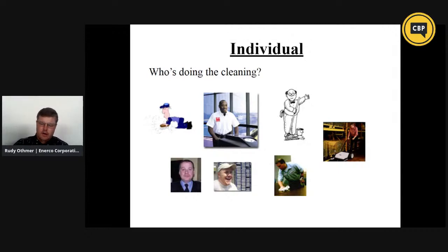and what they are naturally inclined toward. If you're naturally inclined to put tasks off, then recognize that about yourself, and to the extent you can, schedule production in such a way that when it gets time to clean, you aren't tired and you're thinking, oh, it's time to go home, I'll just do it tomorrow. Because it's going to be a whole lot easier if you take the time to run through your cleaning procedure while the tank is still wet and the soils are fresh.